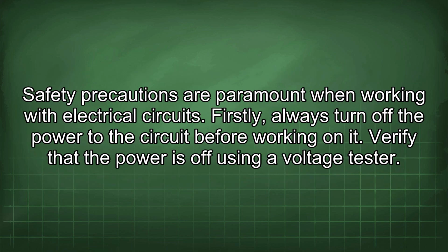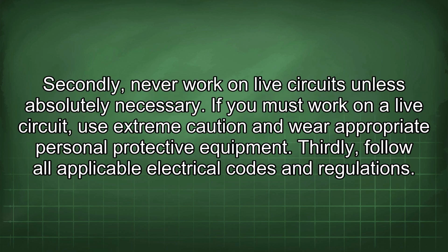Safety precautions are paramount when working with electrical circuits. Firstly, always turn off the power to the circuit before working on it. Verify that the power is off using a voltage tester. Secondly, never work on live circuits unless absolutely necessary. If you must work on a live circuit, use extreme caution and wear appropriate personal protective equipment.